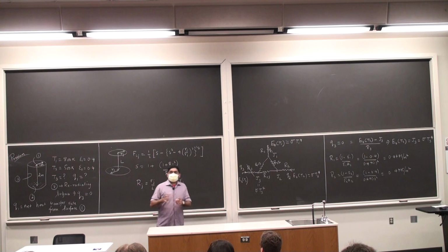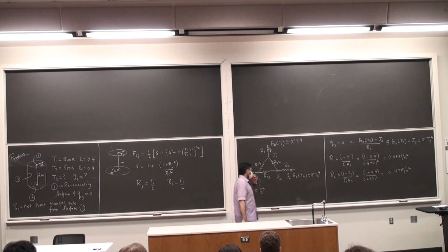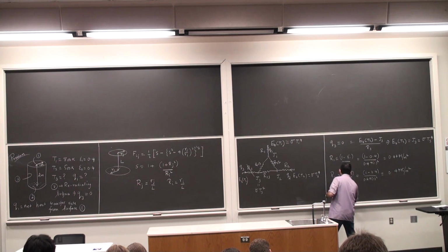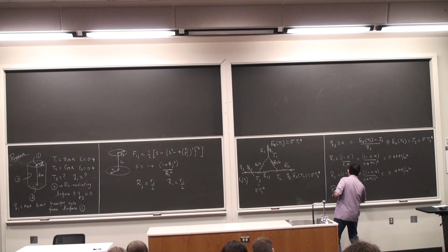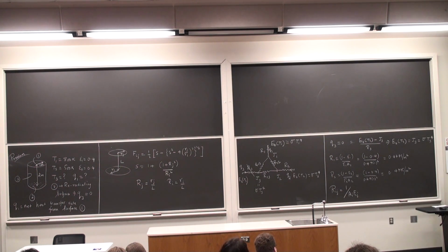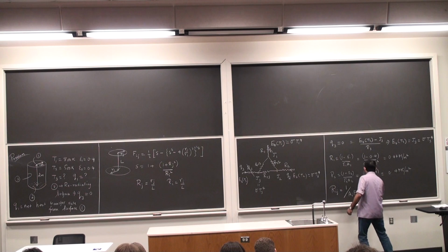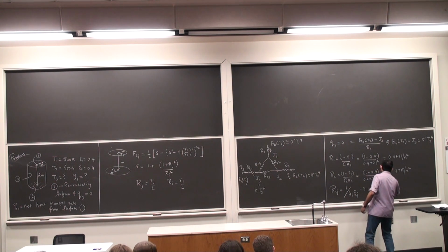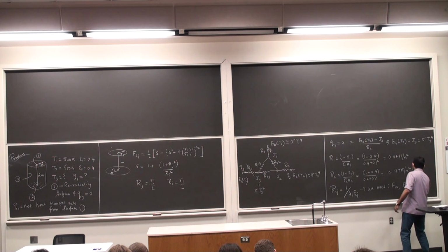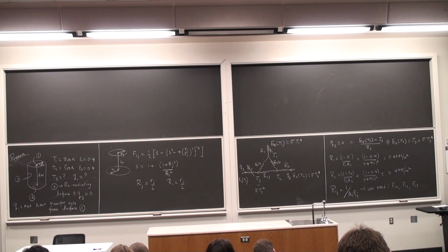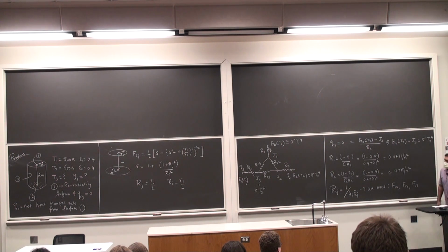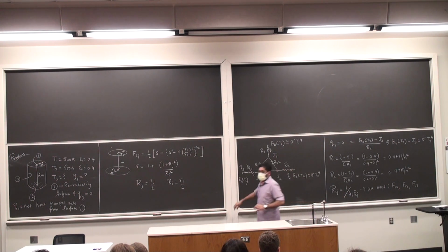To calculate any of these Rij's, I need the view factor. The general formula is Rij equals 1 by Ai Fij, which means I need F13, F23 and then F12, or equivalently F21, F31 and F32. No harm done if you're flipping this, as long as you flip the area as well. And we do that by making use of this formula given for the view factor.